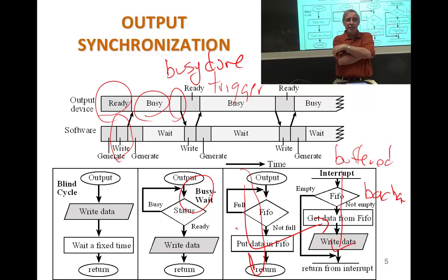One other place that we don't have to do it but I love to use globals, and that's in our debugging. In your Keil debugger, there's a window called Watch. What's that?